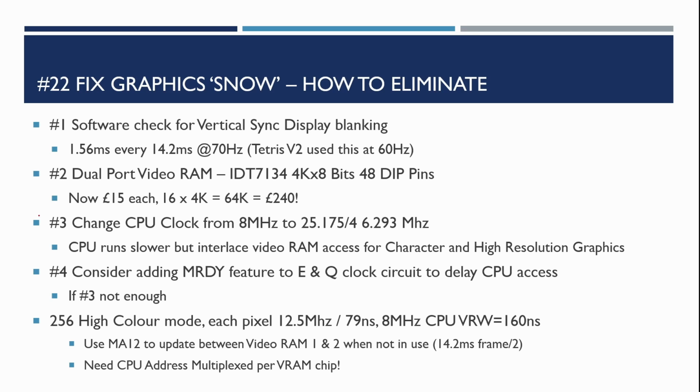In some of the previous videos, we upgraded the CPU clock from 4 megahertz to 8 megahertz. Because we're using chips which are capable of running at this faster frequency, we can now perhaps run the CPU off a clock which is synchronized to the video card. VGA uses a 25 megahertz dot clock. If we divide that by 4, we'll get about a 6.2 megahertz clock.